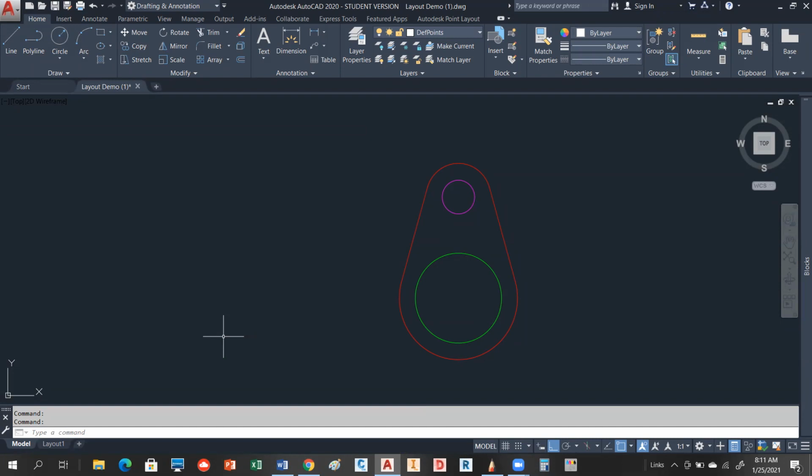Your model also is very important to be fractured out in layers. Instead of just using everything on the same layer in different colors, that doesn't really work very well in paper space. That's why layers become very important. And as we get into Civil 3D, you're going to see layers as an incredibly diverse thing, because they just have layers all over the place.